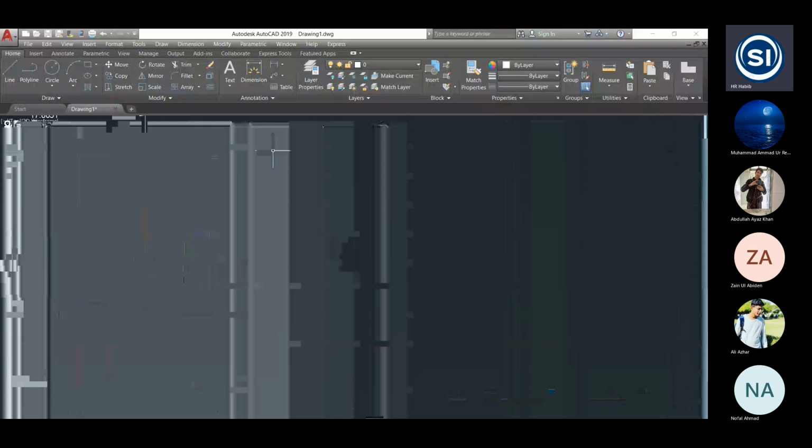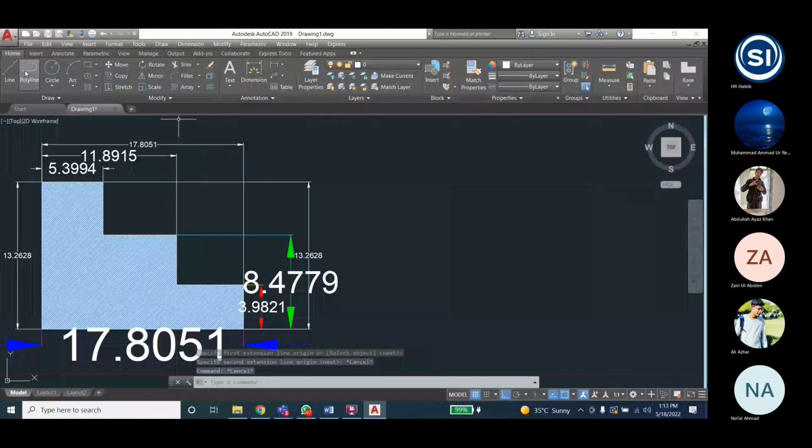Okay, it will be difficult, so to simplify it, first draw a simple line with the line command, separately. Just a simple line command. Okay. Done. Now dimension it, linear. Dimension it, linear. And dimension. This is done. Okay. Done. Yes, sir. Now go to dimension reassociate.